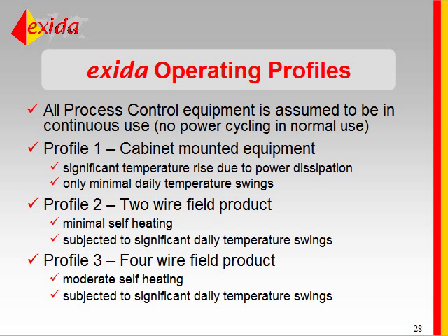In order to deal with category number 3, the product use, operating profiles were defined. And we're talking about environmental profiles. For each specific profile, there are international standards that define temperature ranges, temperature cycling, humidity, electrical stress, surge, electrostatic discharge.